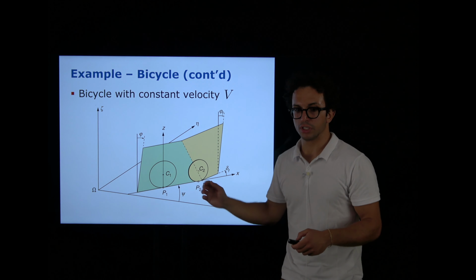Let's start with the neutral model. This is the model coming from the physics, which we introduced last time, and it's exactly the same thing. So we have the A, B, H, R construction. You can find them all here. It's based on the length of the bicycle, the height of the bicycle. Then we have g, which is the gravity acceleration to the ground. So it's basically the gravity force to which the center of mass of the bicycle is subject. And we have v, which is the forward velocity, because the bike is going forward. So it has a constant velocity that we said was 4 meters per second.